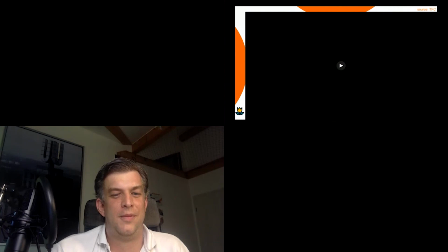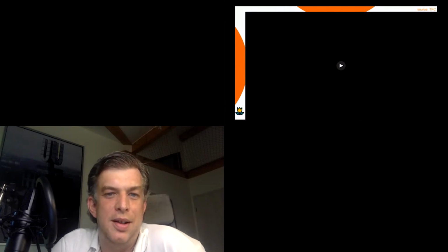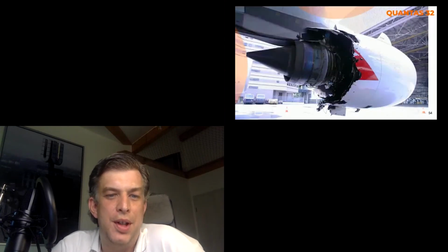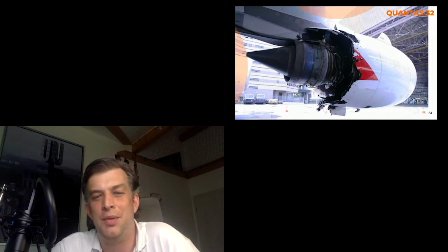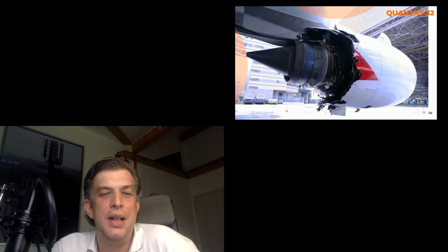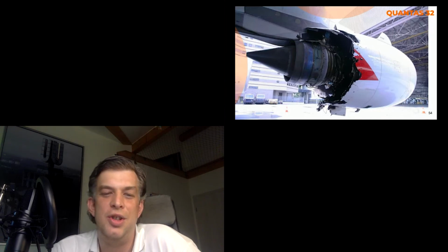When the engine disintegrated, it caused extensive damage to the nacelle, which is where the engine is mounted, the wing, fuel system, landing gear, flight controls, engine controls, and a fire in a fuel tank that self-extinguished. The subsequent investigation concluded that the failure had been caused by a breaking of a stub oil pipe which had been manufactured improperly. The crew was holding for almost 2 hours to assess the situation when the aircraft made a successful emergency landing at Changi.